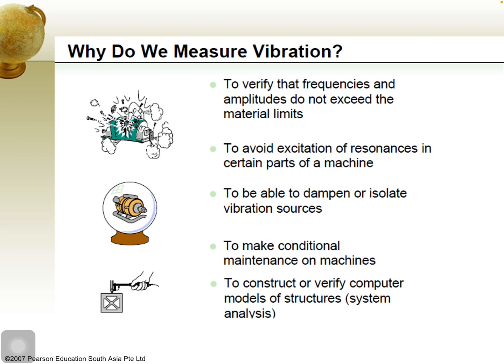Okay, why do we measure vibration? Before this, the three equations were to measure the components of the vibration. We measure vibration to verify that the frequency and amplitude within a machine or within a system do not exceed the material limits.